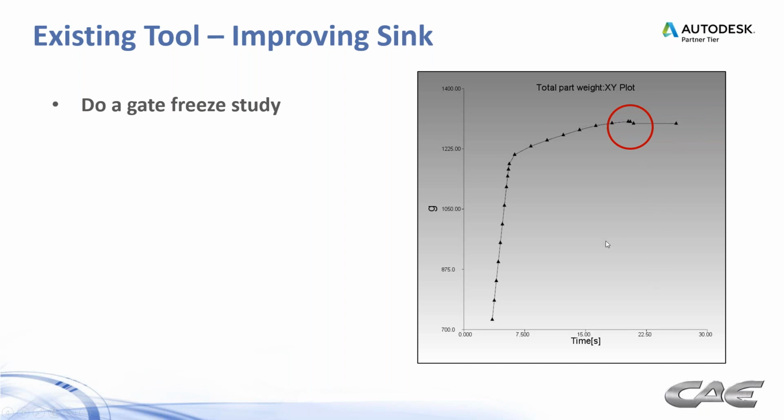So you're not taking full advantage of what the gate is giving you to pack out the part. So make sure you're doing a gate freeze study.